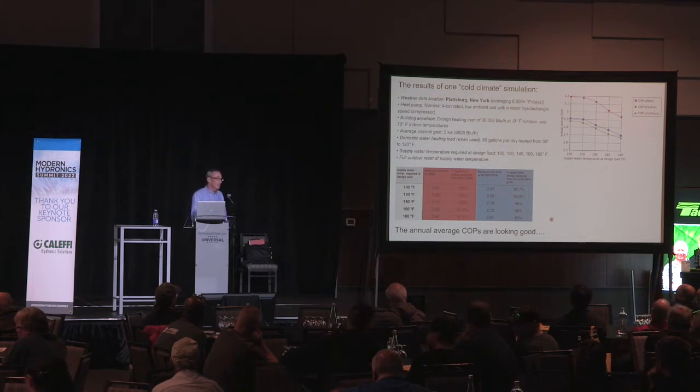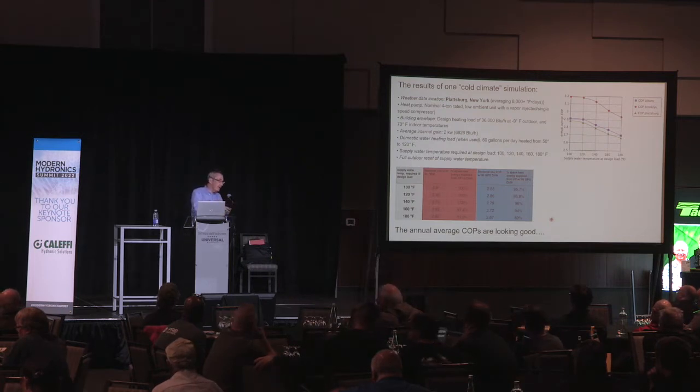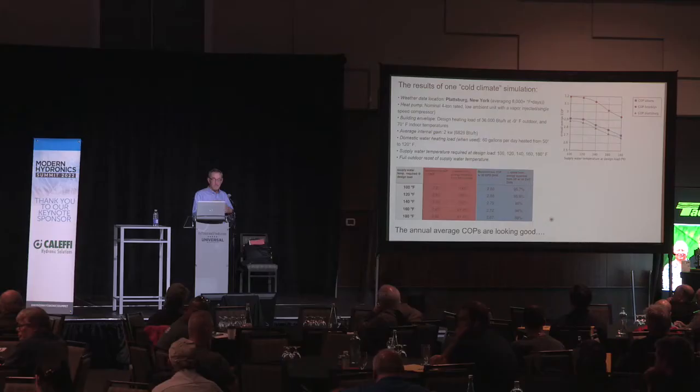So it's a trade-off. If you're willing to either improve the thermal envelope of the building, add heat emitters to the system, or some combination. And in New York State, there's all kinds of incentive programs now, especially for low and moderate income properties, to add insulation, even subsidizing heat pump installation. So if you're willing to do that, you're going to improve the seasonal COP of the heat pump, okay?